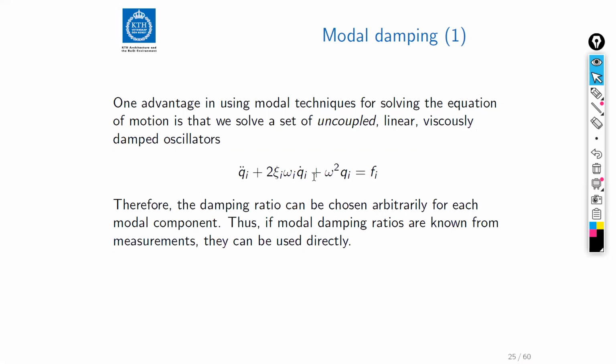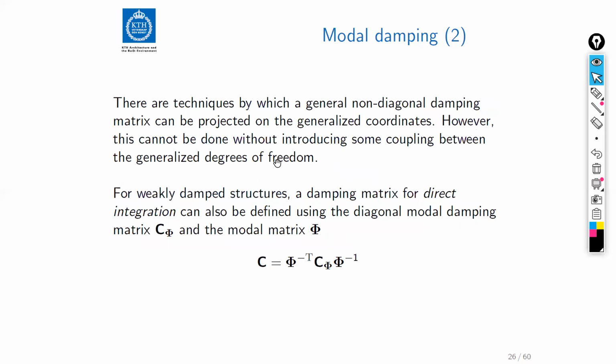We are often given a damping ratio directly from the problem if we start looking into the standards that we are often forced to use. And this is a good thing, really. It's wrong to say responsibility, but in choosing the damping ratio, as I mentioned before, the important thing is that we don't overestimate the damping that we have in the system when we do engineering judgments. So looking for the codes and their recommended lower bounds is a very good place to start.